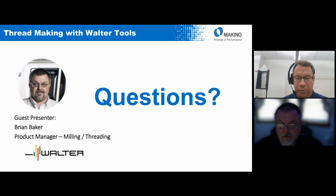Let me close out with one more that's just come in. What about depth as it relates to thread forming? It's a little different, but for the most part, most thread formers can go about 3.5 times D. The ANSI ones are a little shorter, which makes them a little stiffer and a little stronger. They can handle that extra depth. The DIN ones are longer. They can do that as well.